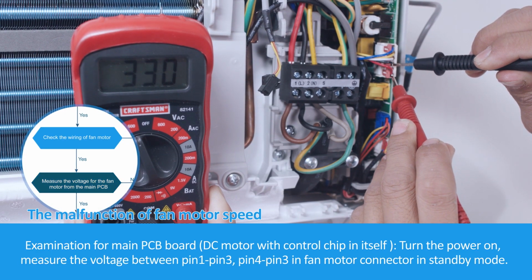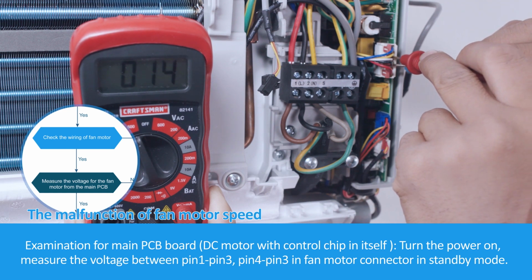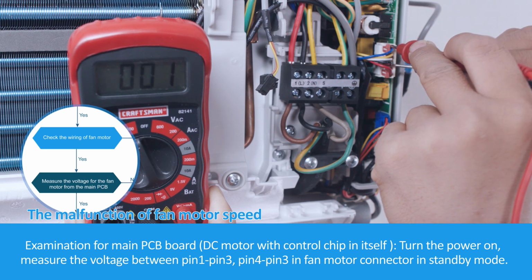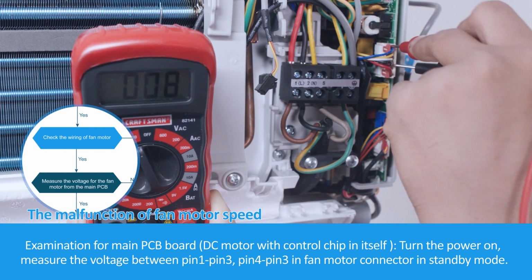Examination for main PCB board. DC motor with control chip in itself. Turn the power on, measure the voltage between pin 1, pin 3, pin 4, pin 3 in the fan motor connector in standby mode.